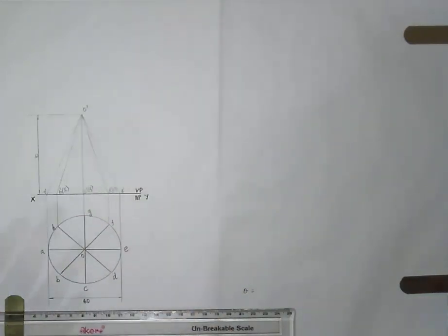That is your wish. You can divide the cone into 12 equal divisions also. But for a development of surface, it is easy to draw the 8 segment circle. So I divided the circle into 8 equal segments, right? So now the cutting plane condition given here is the cutting plane makes an angle of 30 degree to the HP and bisecting the axis.